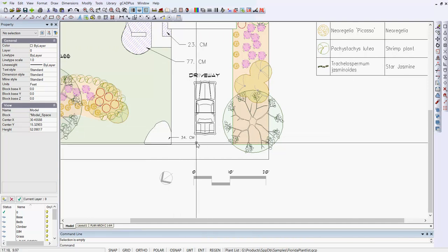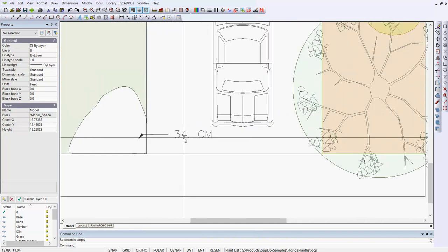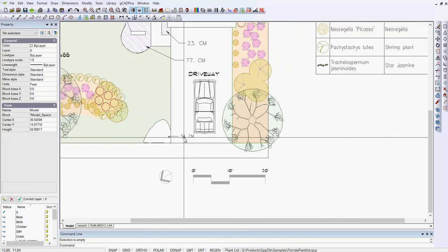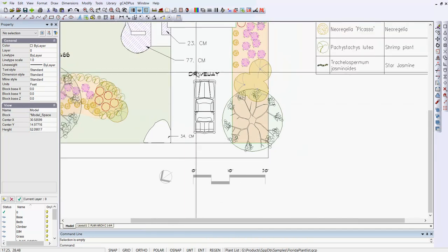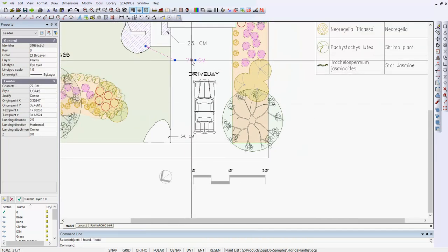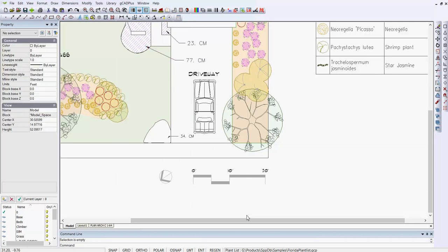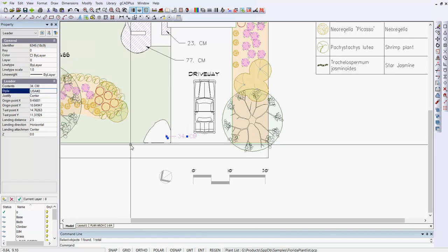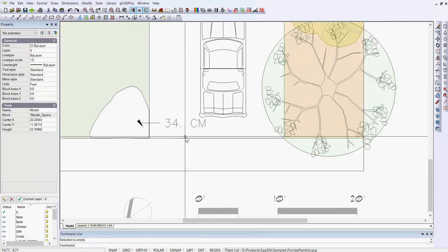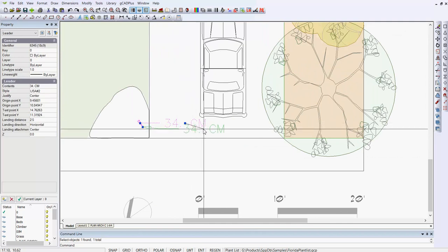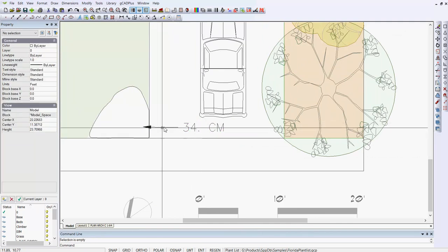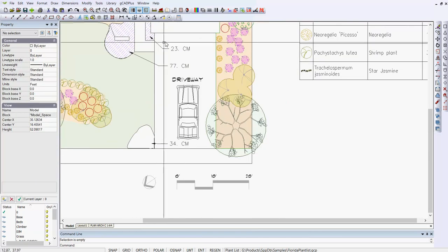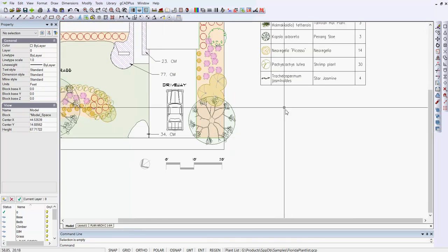And by the way, that's drawn in the current dimension style. You might want to increase the size of text in that; it's using a style called USA2. We might be able to pick this one and just change that style to USA2, and that fixes that up, but we need to stretch the leader out. So we have 3 zones here labelled.